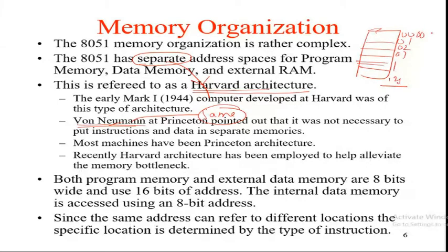Like this, these are not available. How it is available is 00 to 7F. That is the hexadecimal equivalent of 128 is 7F. So these are the memory locations we are having, 00 to 7F. That is nothing but an organization of memory, and as it is separate from the RAM and same for the RAM, that is going to differ with the help of the Harvard architecture. However, in order to handle this particular memory location, we have to define that particular address of memory location only through A0 to A15. That is address lines. That is, you have to use the 16-bit address.